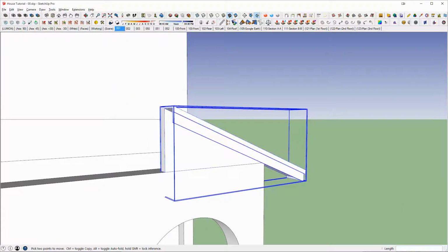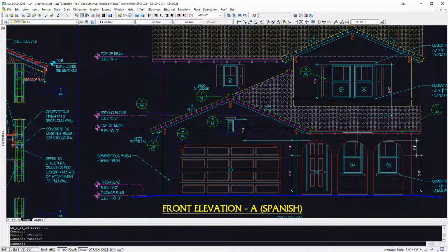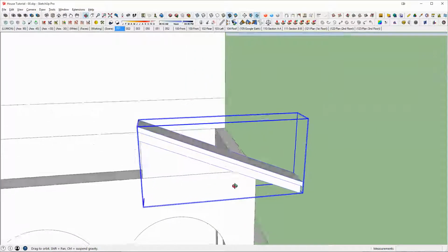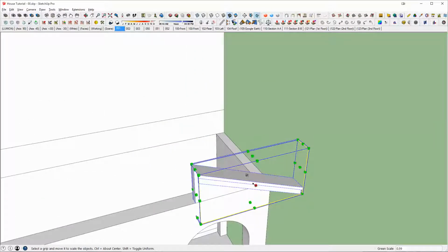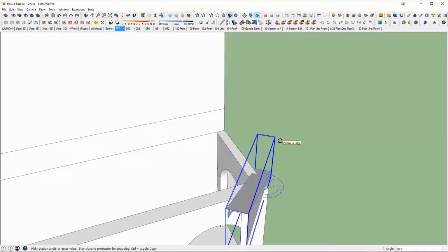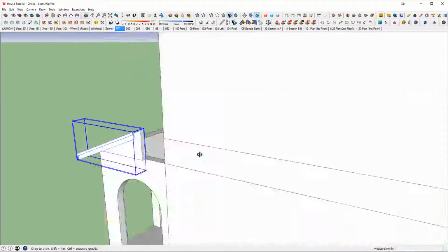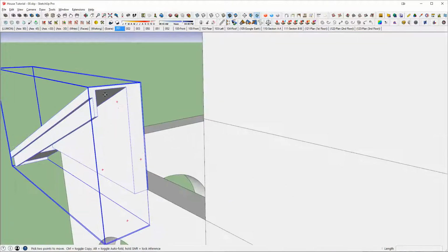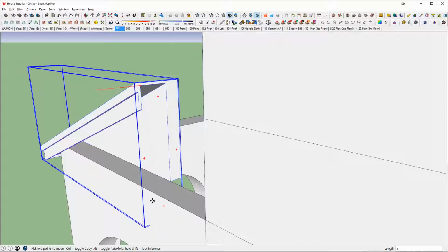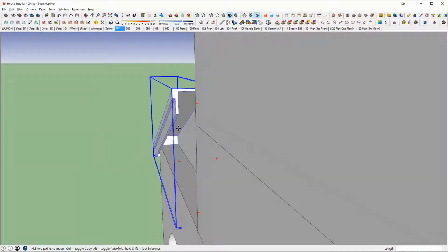I'm going to check my CAD file to see that we're going up that way. And so we actually are going to want to scale that by -1 to mirror, and then we will rotate it by 90, and then this will come and just going to touch this plane right here, and you can see you got, again, a perfect roof that sits.